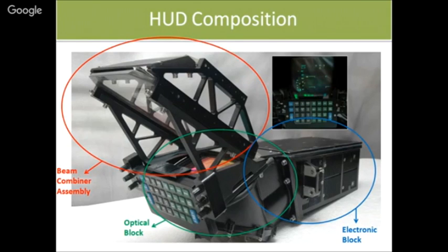I need plus minus 30 volt for something else, reflection amplifiers. I need certain voltages, 1.5K, 1500, 15K, 800 volt for the CRT. All those powers I have to generate from this particular 28 volt input.